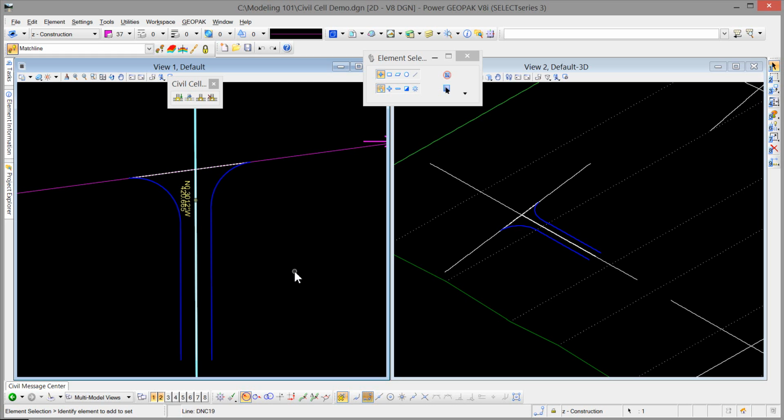And so we make a terrain model, and then to the terrain model we assign a template, just our regular roadway templates. And what it does is it finds the insertion point or the origin of the template and looks straight down and evaluates what it sees and what its thicknesses are. So it doesn't really matter what template I pick. It could be a curb and gutter. It just says, well, under the template origin, I see these particular layers, and this is how thick they are. And that's what it puts in there. And it basically parallels that top terrain.